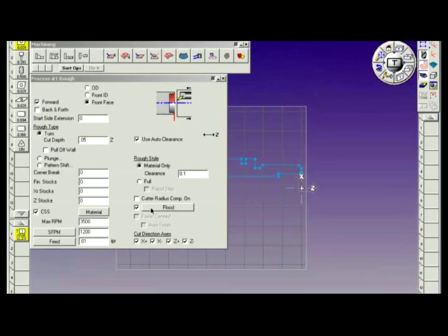That's on. You notice that preferred canned and auto finish are unchecked, and grayed out. They are not active with auto clearance. The reason being is that the preferred canned generates a can cycle, and can cycles require a fixed set point to generate the moves. With auto clearance, we don't have that fixed set point, so we can't use the can cycles.